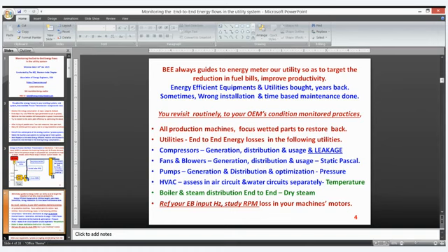On the productivity side, we should maintain and monitor what is the hertz available from the EB side and what is the RPM loss in your machines as a benchmark. A lot of machines have their own energy losses due to slippage in motors, slippage in belts or slippage in the machines as such. This also needs to be monitored by condition monitoring.